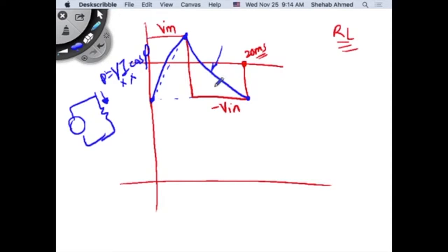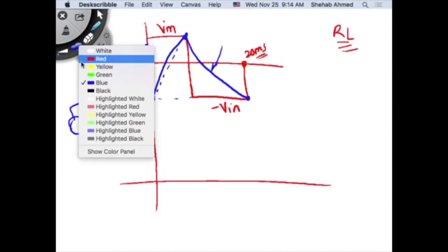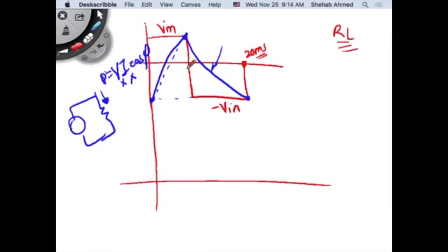So what do we want to do? The load will not change. So the current is sort of dictated upon us, right? The current is going to be dictated by the load. You put a voltage, you create a current. So ideally, I would like to be able to create a nice, beautiful sine wave. That's ideal, right? But before doing that, people developed this in stages. So first we had this 4-switch inverter operating at the fundamental frequency of the output.